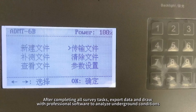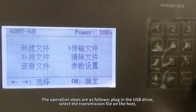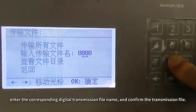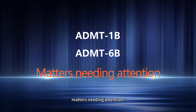After completing all survey tasks, export data and draw with professional software to analyze underground conditions. The operation steps are as follows. Plug in the USB drive, select the transmission file on the host, enter the corresponding digital transmission file name, and confirm the transmission file. Matters needing attention.